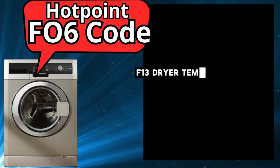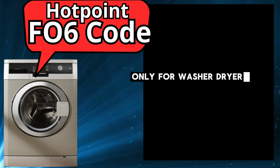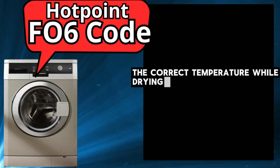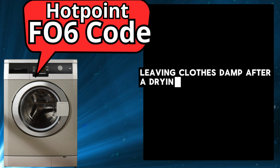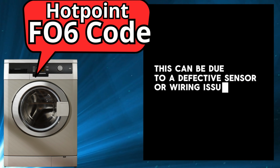F13, dryer temperature sensor fault. For washer-dryers only. For washer-dryer models, an F13 error signifies that the appliance is unable to sense the correct temperature while drying clothes. As a result, the dryer function may not work effectively, leaving clothes damp after a drying cycle. This can be due to a defective sensor or wiring issue.